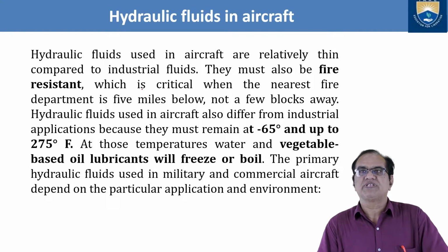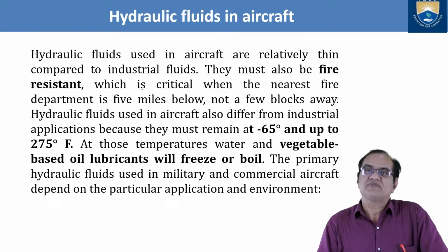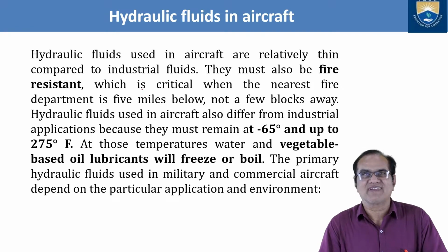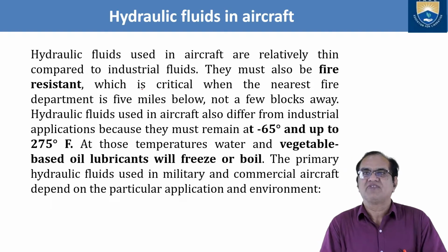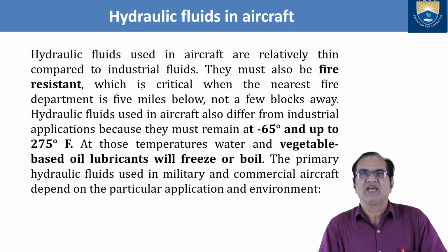Because you are flying, there is no firefighting system there. If you are flying 100 kilometers away, the firefighting team cannot reach you. So you should make sure that there is no fire risk during flight. Hydraulic fluids used in aircraft also differ from industrial applications because they must remain usable from minus 65 degrees up to 275 degrees Fahrenheit.